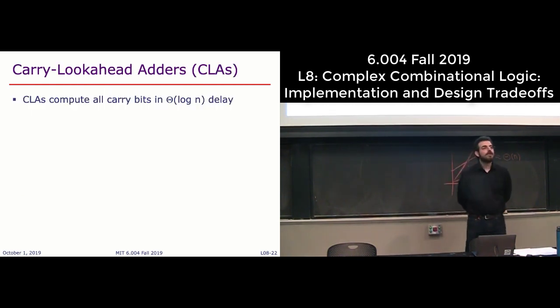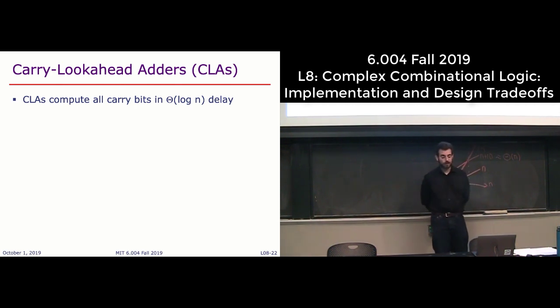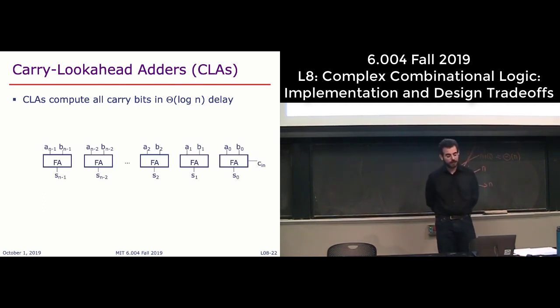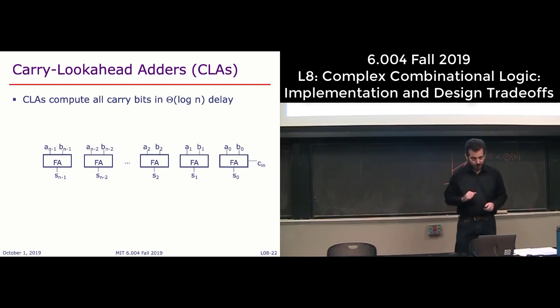So let me introduce, in the last few minutes of the lecture, the most sophisticated type of adder, which is one that I recommend you build. And we'll finish the discussion of this in recitation. But let's see the key insight of carry look ahead adders, which is actually a very general insight. What we want is to have some circuitry that computes all the carry bits in logarithmic time. Now we've seen a way to compute the whole addition in logarithmic time, so hopefully that's possible, right?